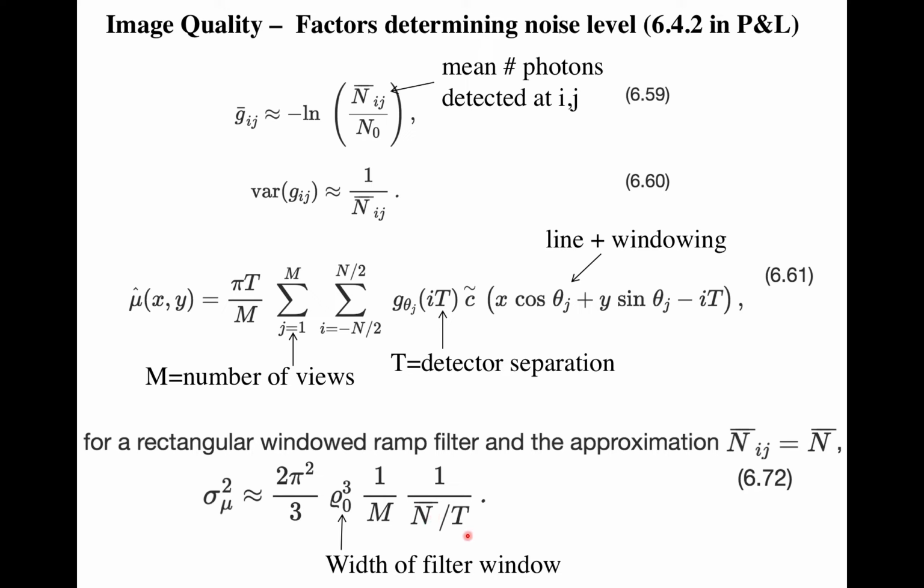Detector width: if we just say, hey, I want a higher resolution picture, I'll make the detector width half, right? Well, that's going to pull this down, because you got to split this between 2 detectors now. So it doesn't come for free, right? So you have to take that into consideration. But if this ratio stays the same, you don't change the signal to noise, right?